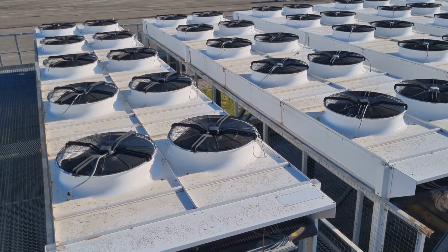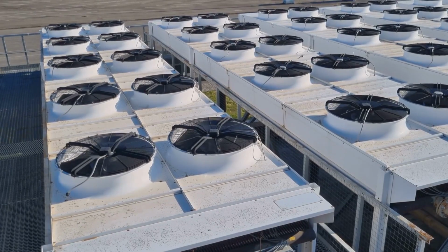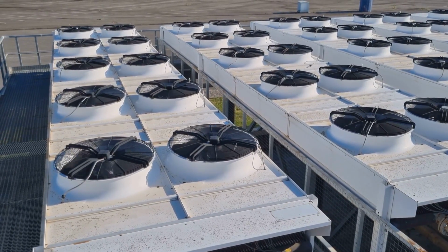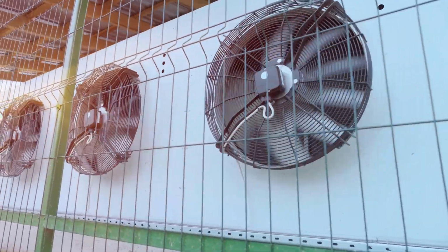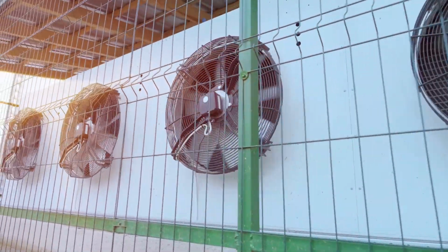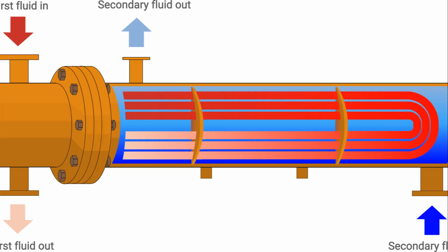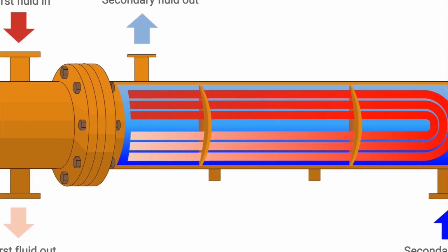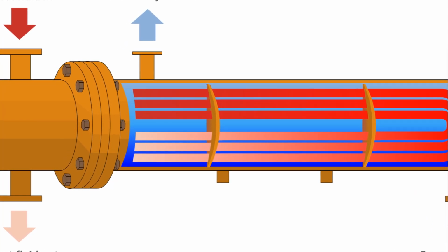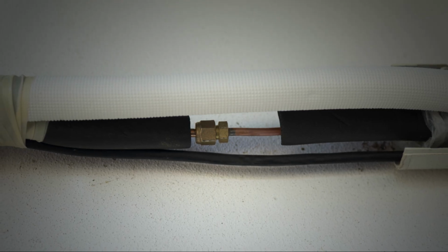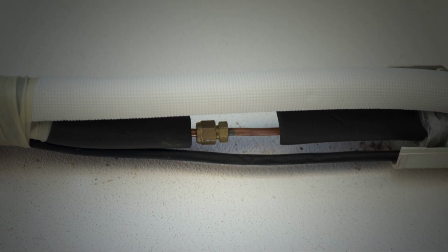When passive cooling isn't enough, active cooling systems come into play. These systems actively remove heat using mechanical or fluid-based solutions. These may include implementing forced air cooling, using fans and blowers to circulate air and remove trapped heat. Liquid cooling, pumping coolant through heat exchangers to absorb and transfer heat away from critical components. Phase change cooling, leveraging refrigerants or heat pipes to move heat more efficiently.